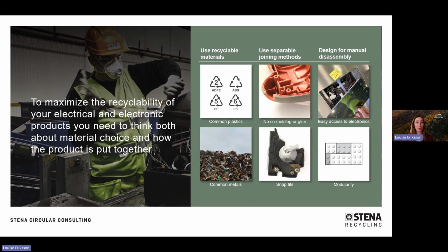Also for the big volume metals, same thing there. The second part is about the joining methods. So here we encourage you to use separable joining methods. This means to avoid co-molding or gluing different materials together.